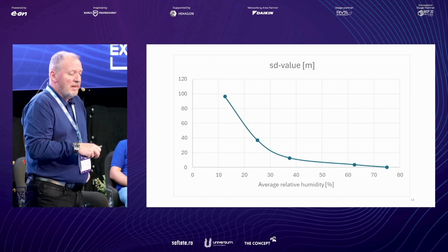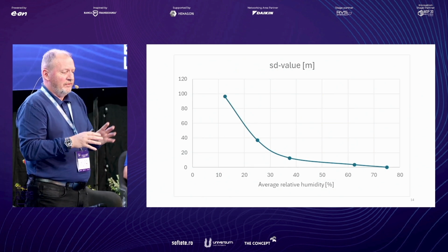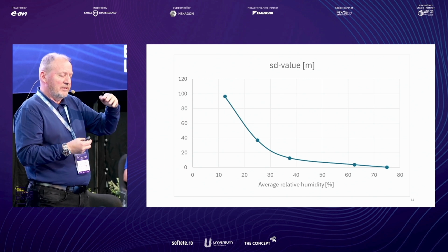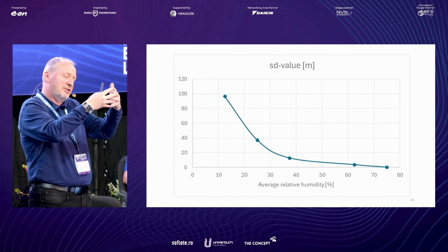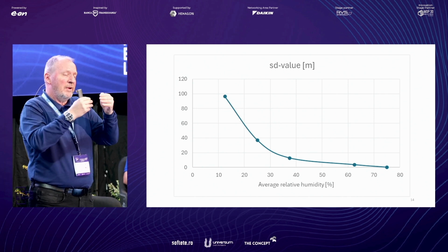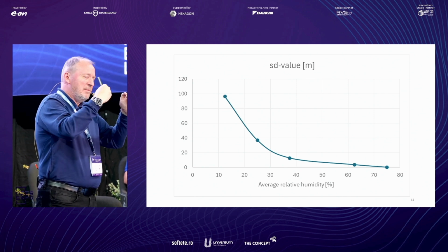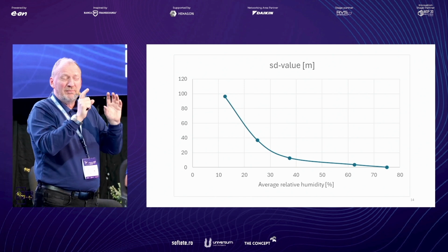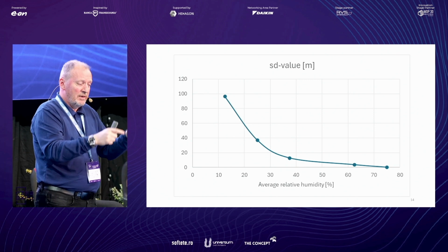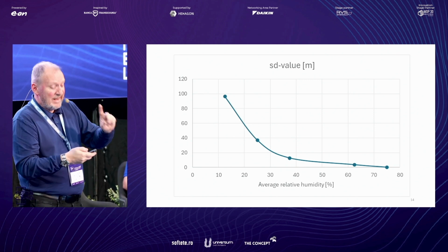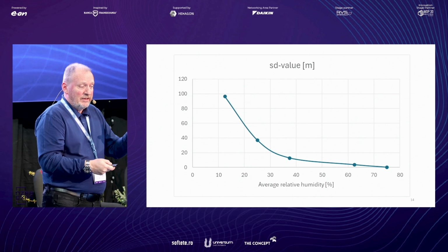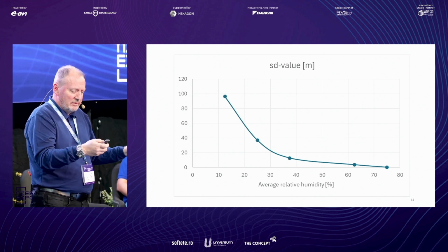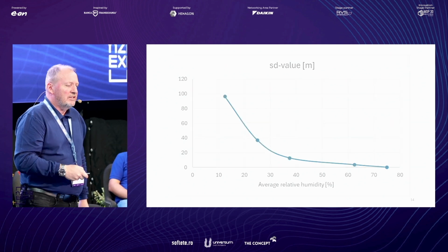In actual fact, this is a fairly typical graph of some products that we see, where you can see as the humidity increases, the material itself is able to change state, which is nice, allowing any trapped moisture to escape into the building. And because you're making airtight buildings, you can control that with ventilation rather than leakage, and it takes care of the moisture internally, which is a nice feature. You get the benefit of airtightness and vapor control year-round. It's not just a winter benefit, it is a year-round benefit.